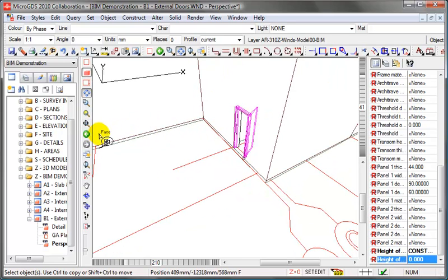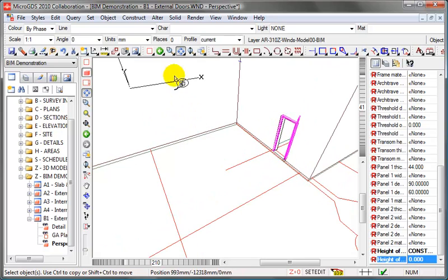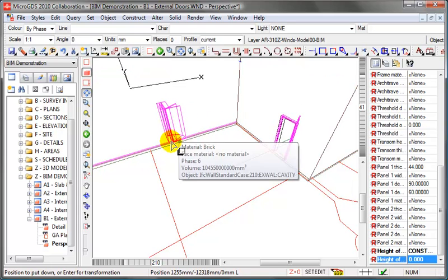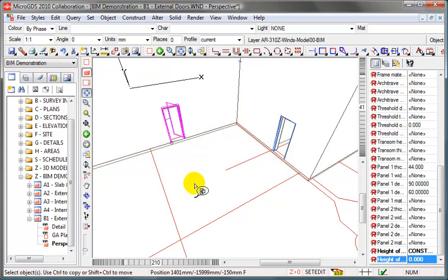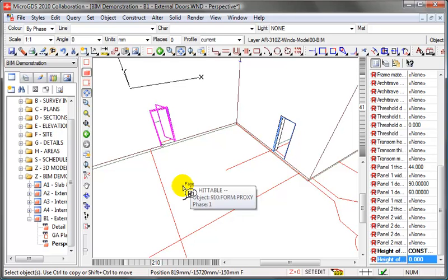I want to make a copy of that door now for our fire escape. It's going to be close to the grid line here, so all we do is use our repeat command, snap anywhere on the door, it doesn't matter because it's constrained, and snap onto the wall, and it automatically adjusts the wall orientation, the door orientation shall we say, to match the wall. And again we can click to drag it into position, and again you can snap positions that you have to make the dimensions relative or set coordinates and so on.